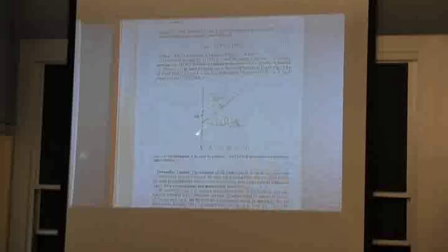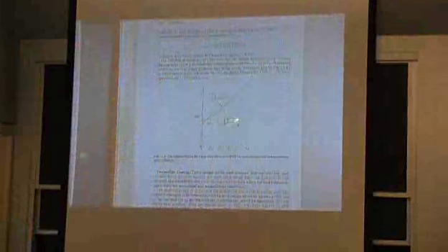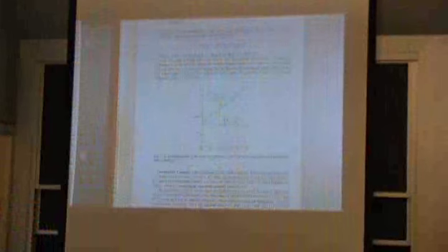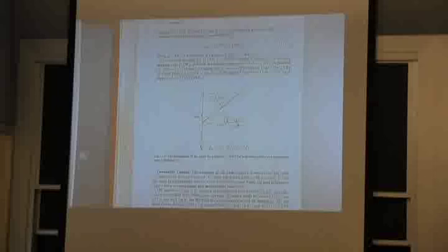You have two typical failure points. One is right up here at the base of the flat wall, so that's the top of the cup up here, and the other is at the bottom of the cup. You don't usually get a fracture in the middle of the wall, okay? You'll get it at the corners, partly because you have stress concentrations at the corners.